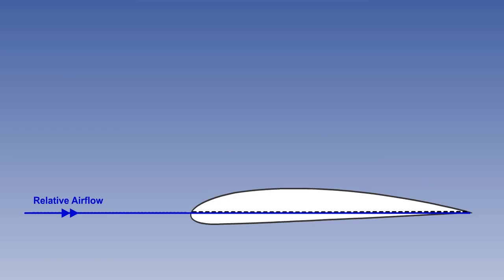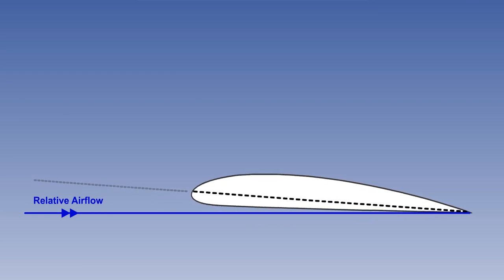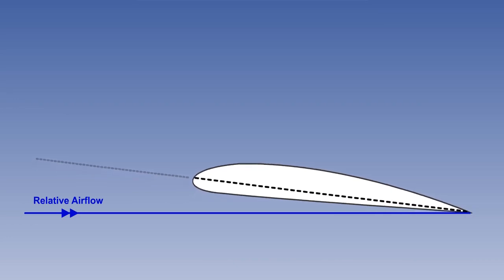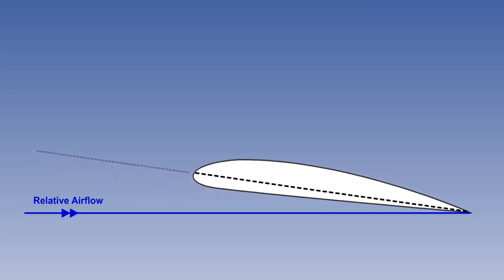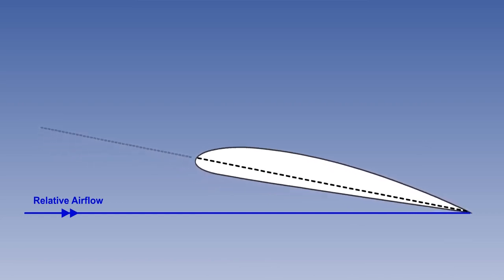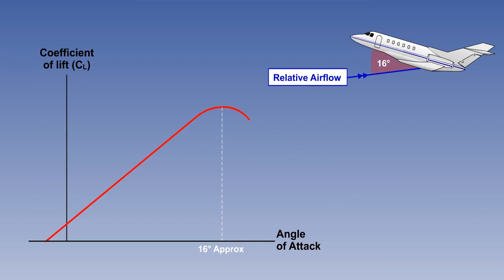At any specific angle of attack, the airflow over some percentage of the wing surface will generate lift, as well as some amount of drag. For subsonic flight, both lift and drag coefficients increase as the angle of attack becomes larger. Maximum lift is usually obtained at a relatively high angle of attack. If the angle of attack is increased beyond this point, even by a small amount, the coefficient of lift reduces abruptly.